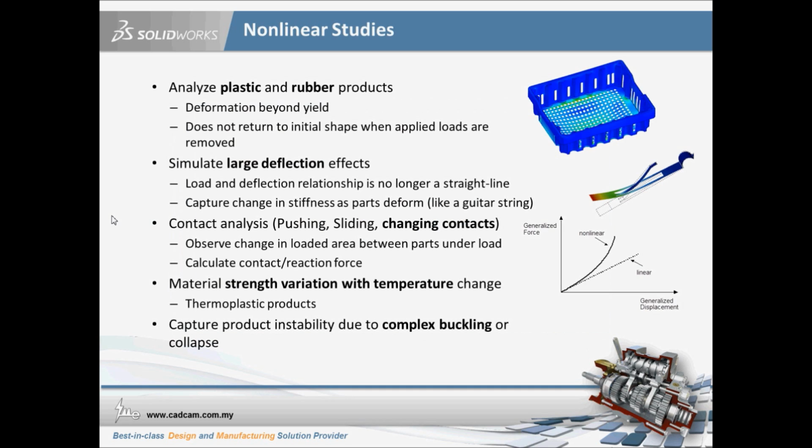Nonlinear study. Nowadays, a lot of consumer parts are replaced by plastic components. Or let's say our consumer parts, we have rubbers, gaskets, those kinds of things. So nonlinear study is for us to analyze plastic and rubber products, especially on deformations beyond the yield strength, and it can also be used to simulate large deflection.